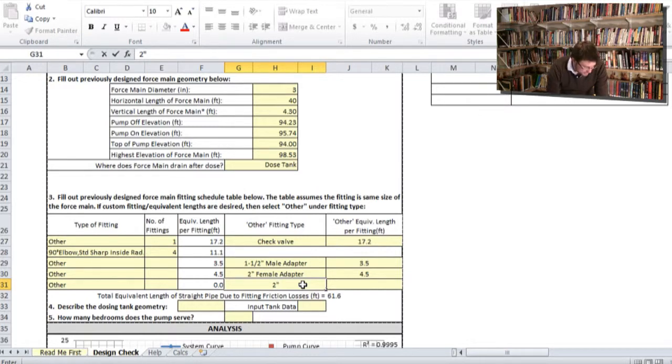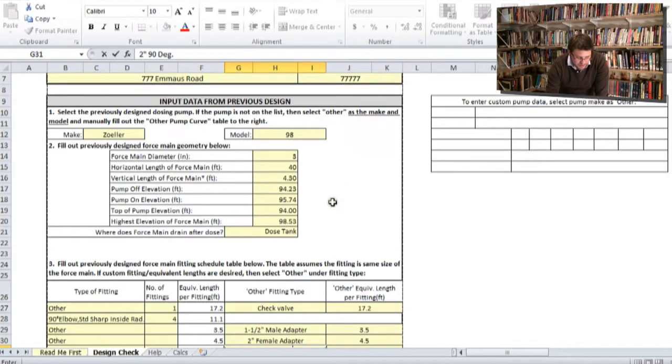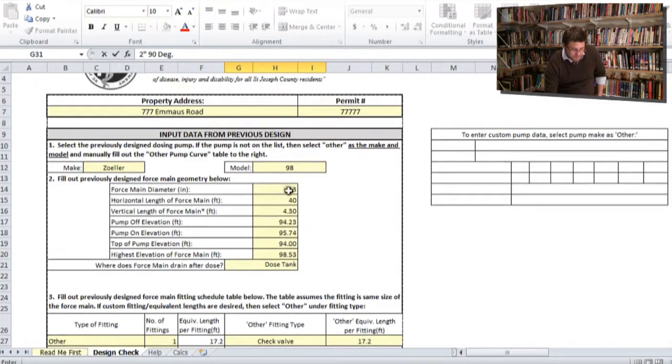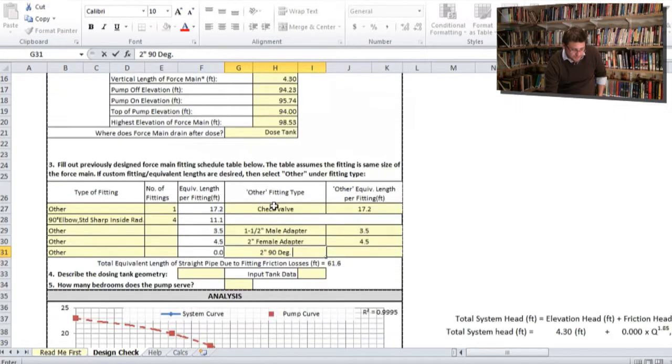this is an interesting situation here, because he has a pump, this $1.98 pump, that has a discharge. It appears to me to be a 1.5 inch discharge size, and so then he puts an adapter to a 2 inch, and then his 2 inch goes to a 3 inch pipe, which is where he's getting his 3 inch force main.